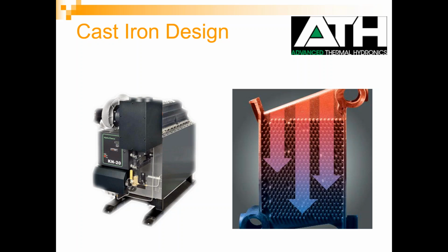Cast iron has been used in boilers for over 100 and some years now. It's a very forgiving material, and it provides a very nice product, and you can also do a primary variable flow with a cast iron heat exchanger. It's not quite as efficient as some of the stainless steel products we've showed you from like Riello, but it provides for some very interesting advantages and some nice longevity.